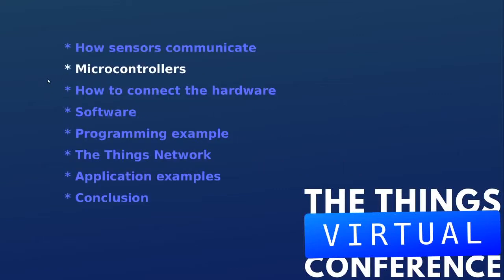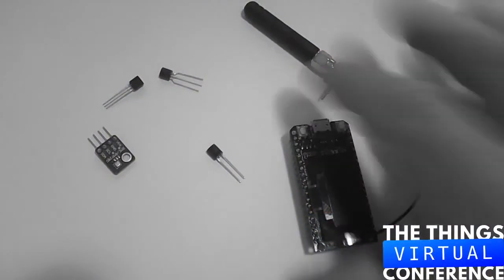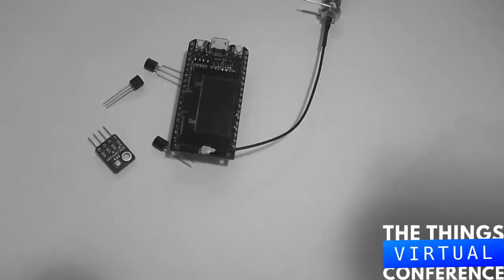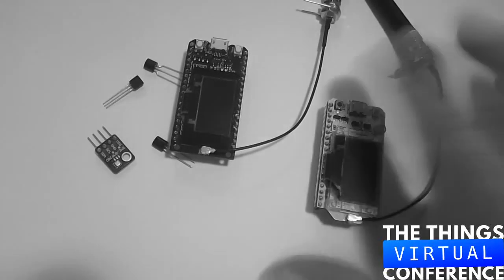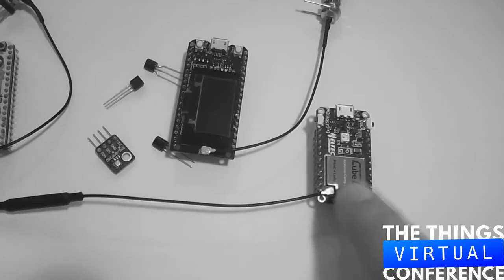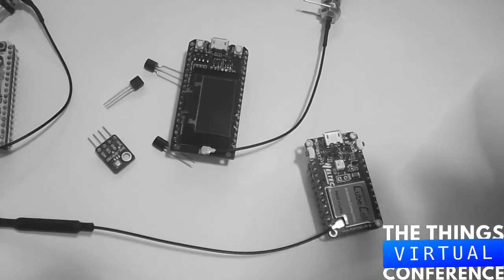Okay, let's go on to the microcontrollers. It's about finding some microcontrollers that work with LoRa, and in some of them the LoRa sending unit is integrated together with the microcontroller, so a small CPU. And that can look something like this. This is the TTGO LoRa 32, which has the same pin configuration as the Heltec WiFi LoRa 32, so they are swappable, in version 1 at least of these. And you can find something like I have here, the CubeCell. It's from Heltec also, and that's the development board. If you order it, order it as a development board, otherwise you will not be able to use it.